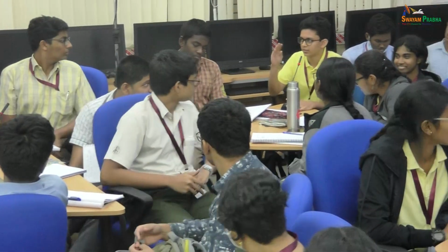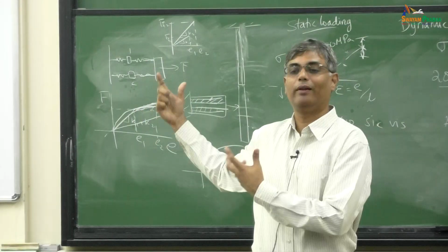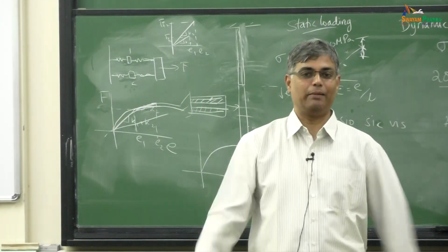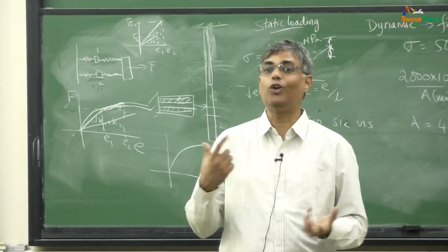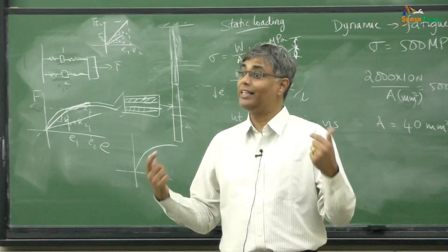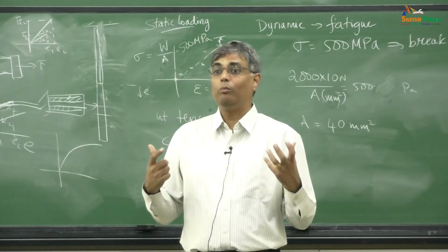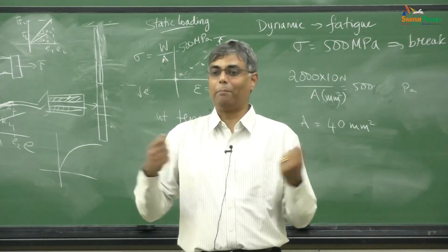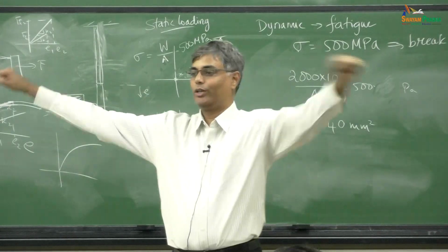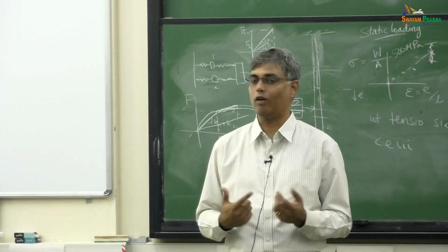I think there are recent discoveries of self-healing polymers. In that case, how do you calculate the stress? Very good question. The reason I gave you a very simple example of fatigue failure was in a normal steel bar. But I am also very interested in very novel materials. People are building materials constantly. There's something called shape memory alloys, materials which can remember their shape. Look up some YouTube videos on shape memory alloys. Very interesting. They are almost as strong as steel, but will deform like rubber. You can make a nice shape, stretch it out, put it in a hot cup of water, and it will come back to the original shape.